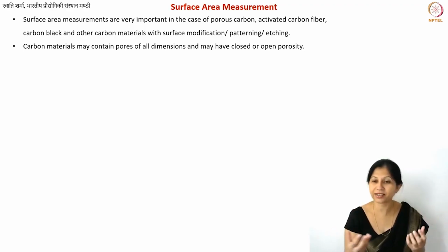This is also a very interesting subject for surface area measurement, because when you increase porosity, sometimes it's just one type of pore whose number or fraction increases, and sometimes it's the fraction of all types of pores that increases. That would depend upon your activation method, and also upon the type of carbon it is, whether it is formed by the charring process, the coking process, or whether it is a very highly graphitic material.